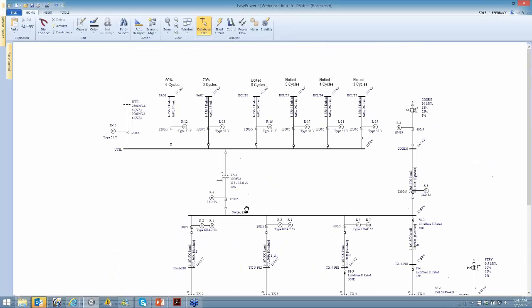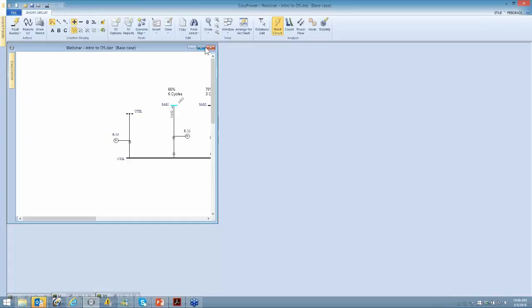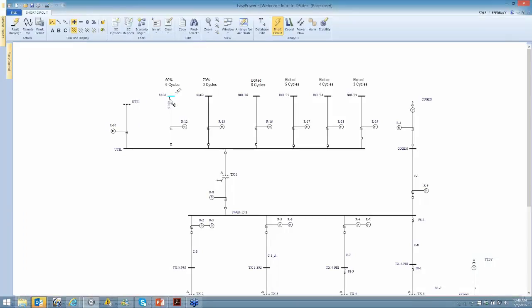One of the techniques in modeling, if we want to simulate a sag on the utility line, is to model a very long run of a transmission line, put a fault on it that will generate a predetermined amount of current. For instance, if we fault this in short circuit, we can see how much current it generates, and it will be cleared by this relay.